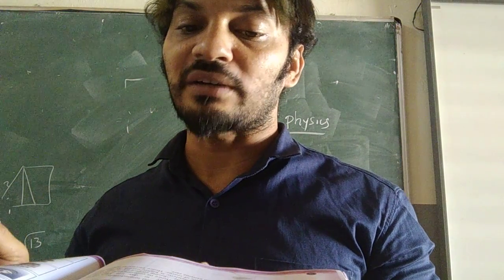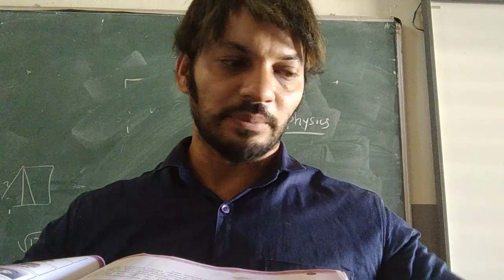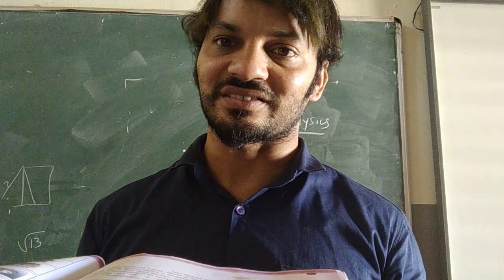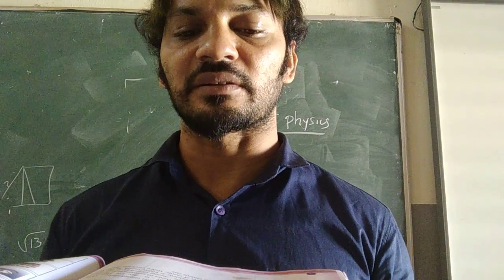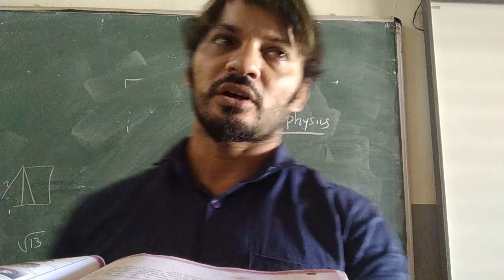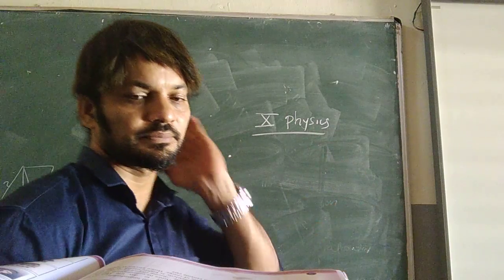Otherwise, the muscles of the body also contract. Muscles will become loose, so the person loses consciousness and becomes unconscious. First aid should be given only after disconnecting the victim from the electric shock wire. When a person gets an electric shock, first of all we have to disconnect him.